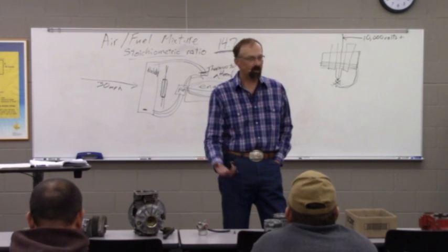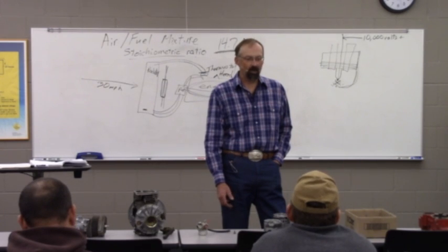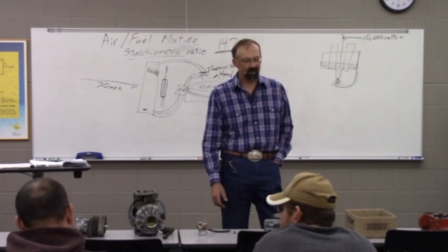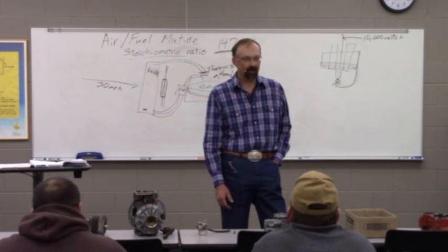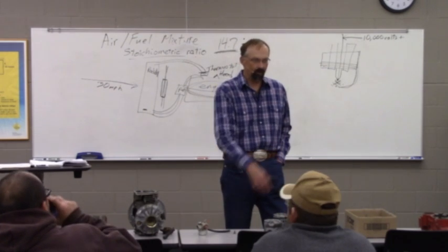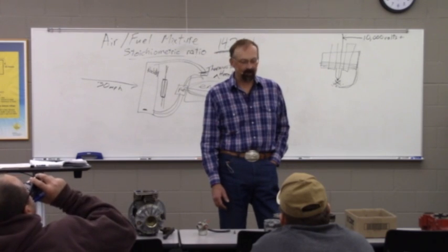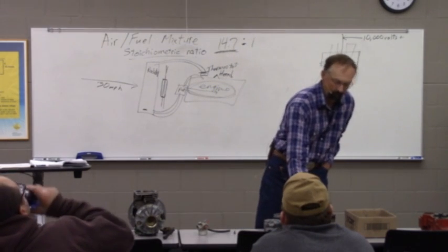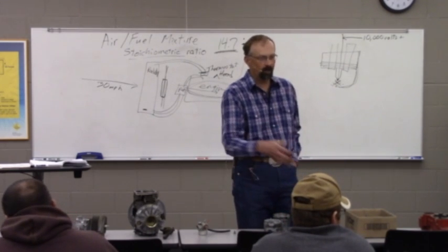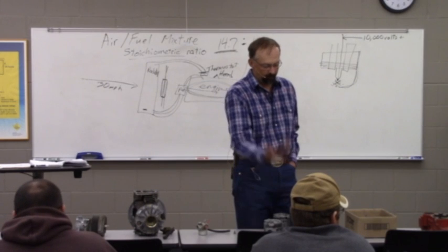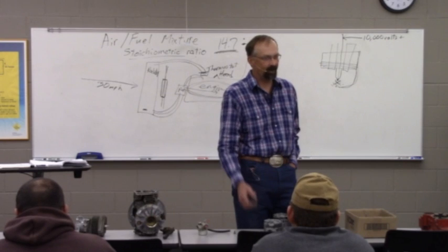Other than the cost of the oil, that's probably the only drawback. But this has been extremely rare, we have seen a few engines that were converted to synthetic and they started using oil. We've guessed that had something to do with the way the rings had been broken in using the other oil, and it was passing the synthetic past them, but that's been very few engines.